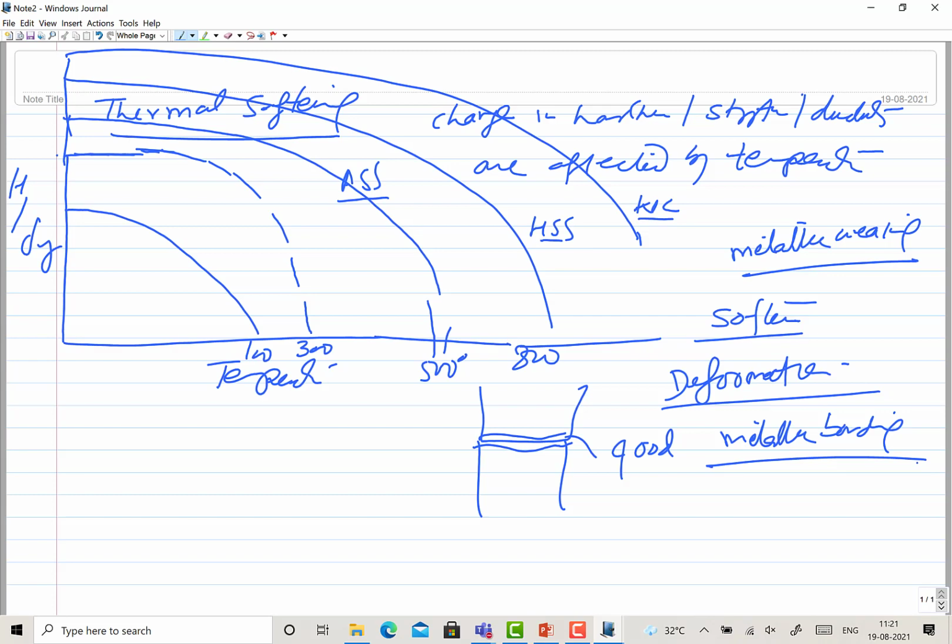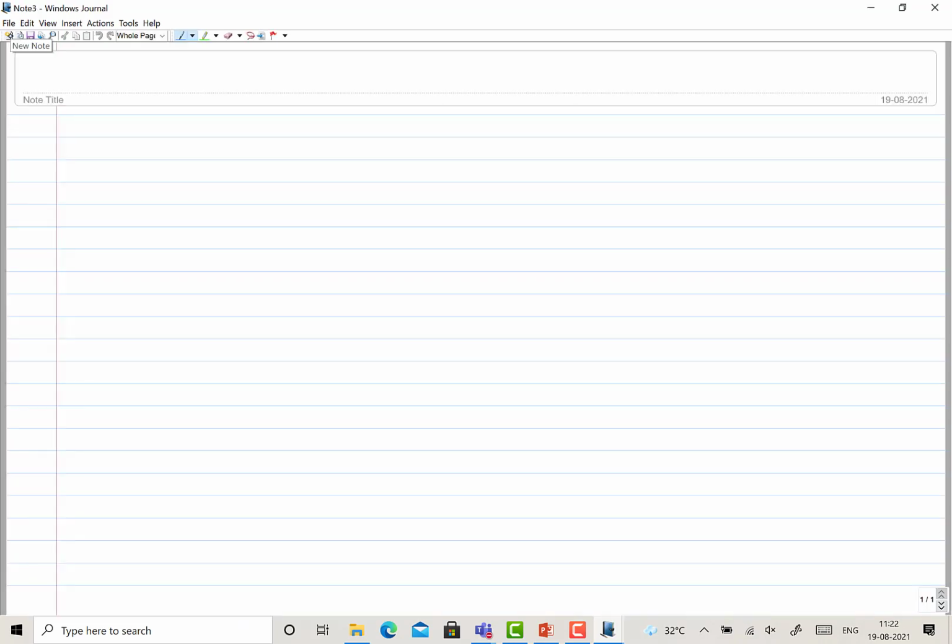So this is another aspect. What we talked about earlier, work hardening, was resisting the deformation and making metallic closeness and intimacy difficult. On the other hand, thermal softening is just the opposite. Each metal shows a different kind of hardening and softening behavior, and that is why you may find a lot of difference in the ease of joining by solid state joining techniques.